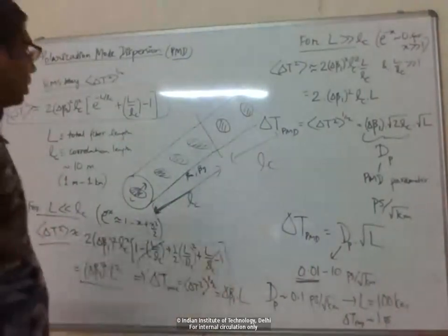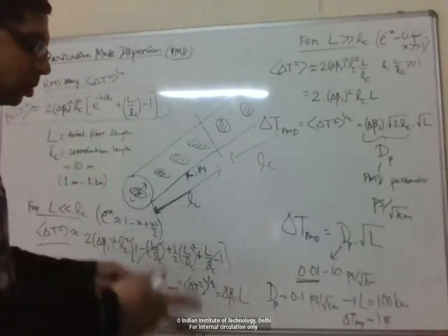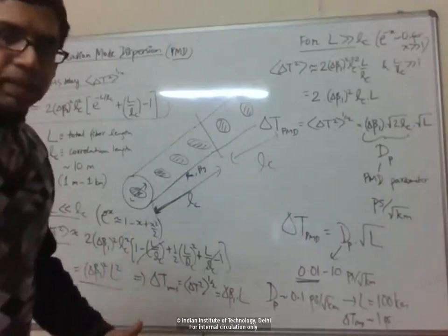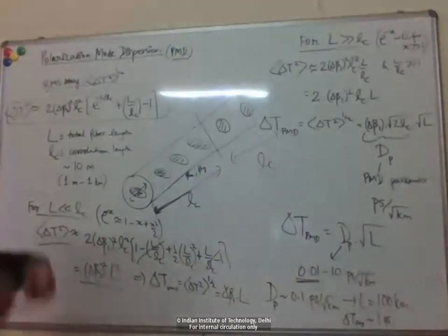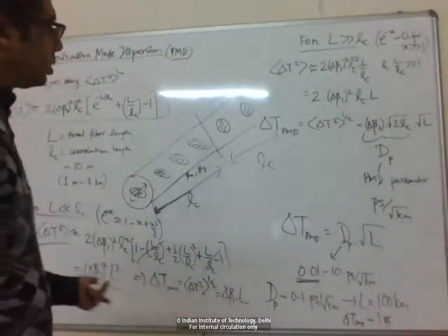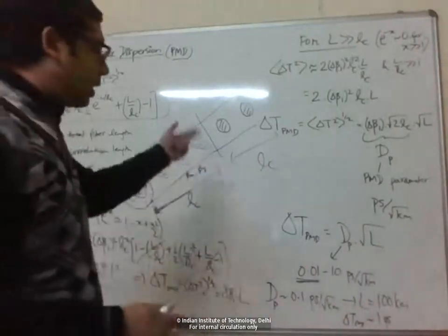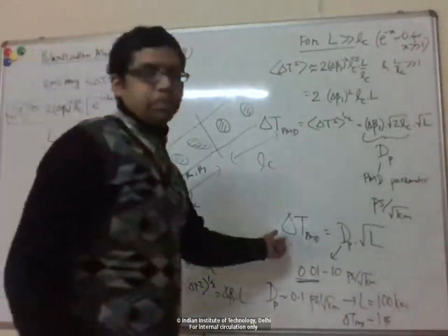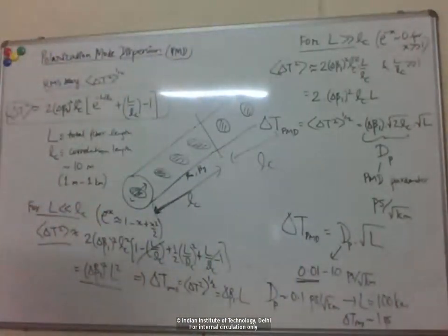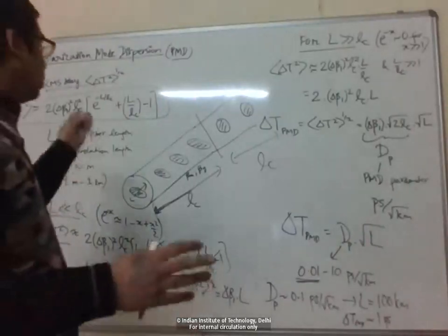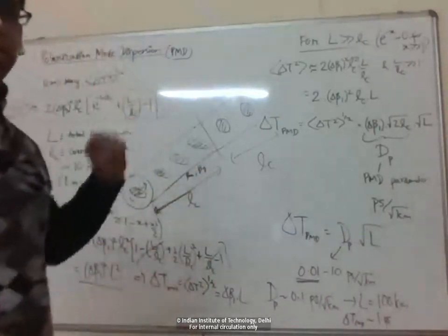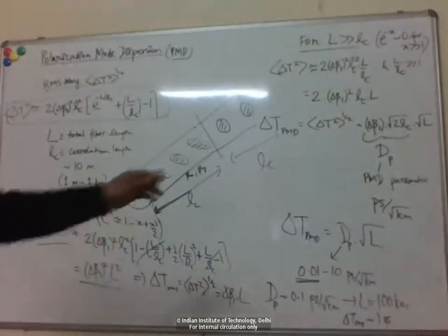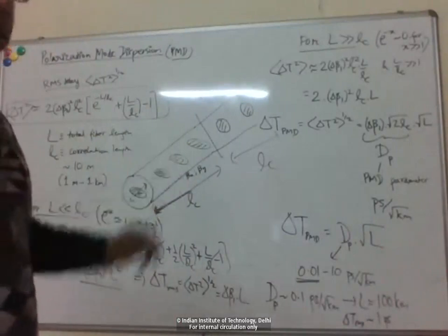The next level is when we go to single mode fibers, where we've eliminated intermodal dispersion and just have intramodal or chromatic dispersion. If we've also compensated for chromatic dispersion, or we're operating near the zero dispersion, then the next order effect is polarization mode dispersion. If you have another mode, that will also have its own PMD, but here we typically talk about just the single mode fiber.